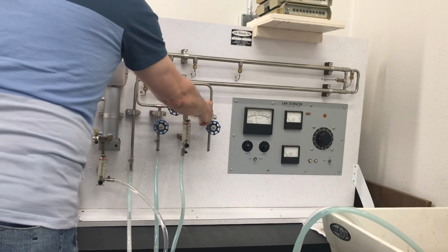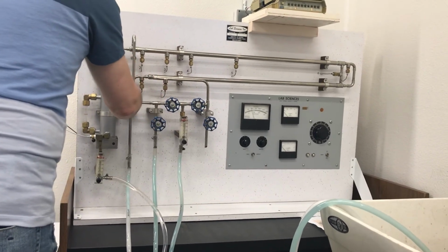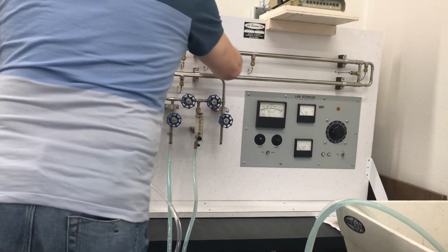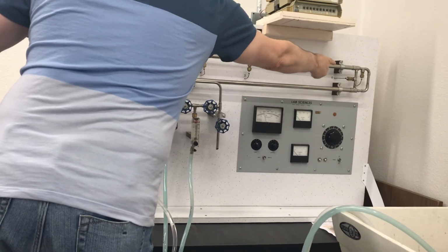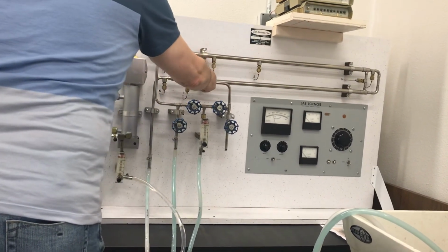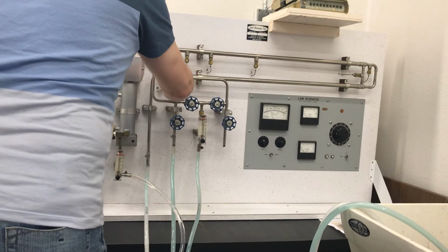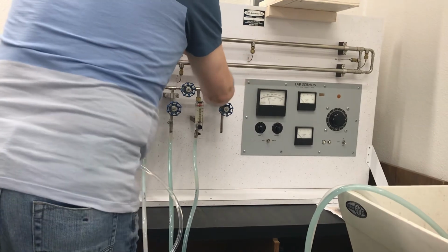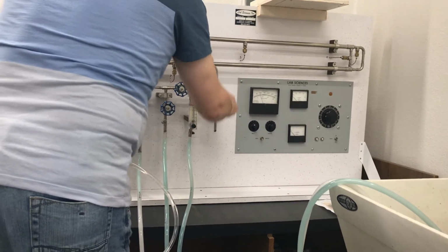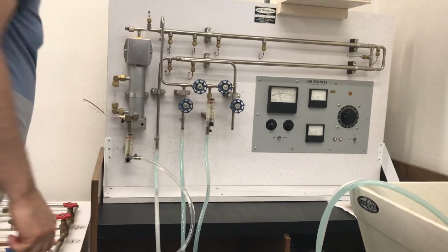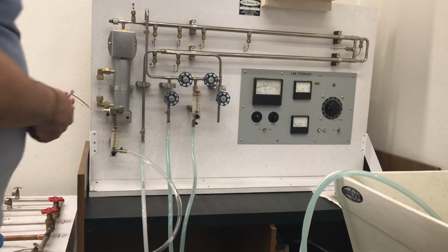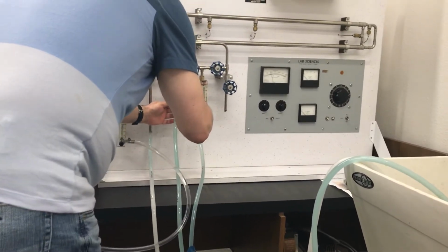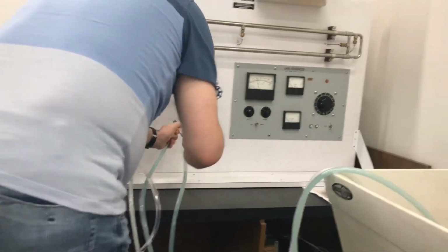So that's closed, and the cold fluid comes in through here, enters the jacket, flows, and comes back through here and back through the jacket. Now it has to decide where to go. Because this guy is already closed, it can only go through here. So what we typically do, so that we don't make a mess, is that the cold out has to be switched to here.